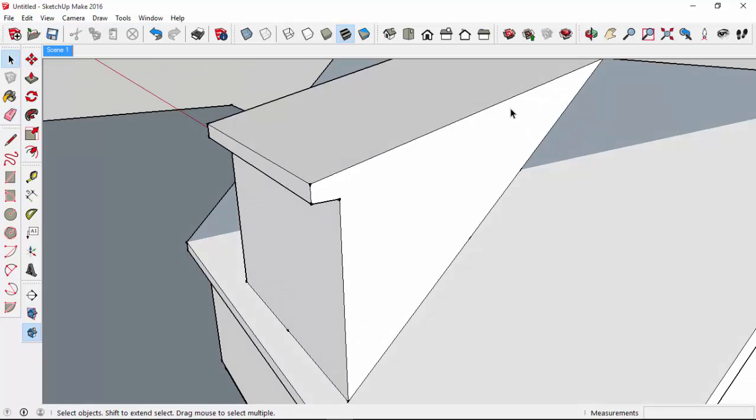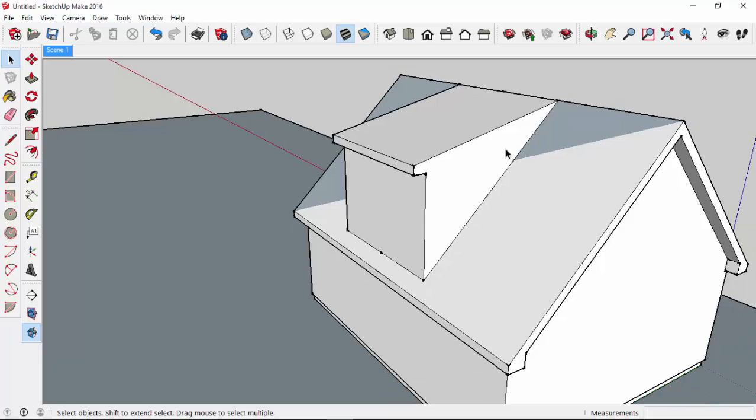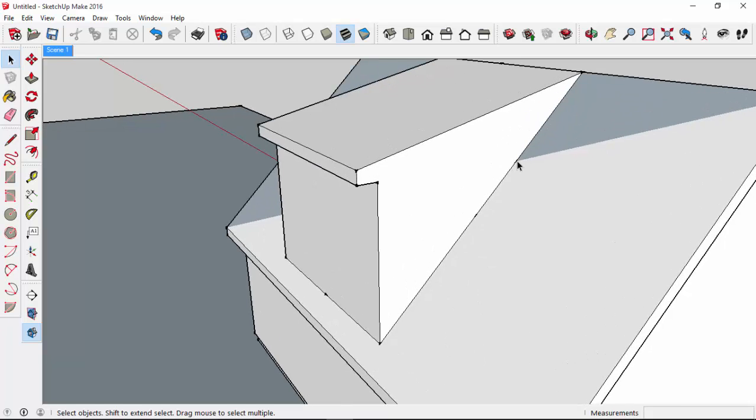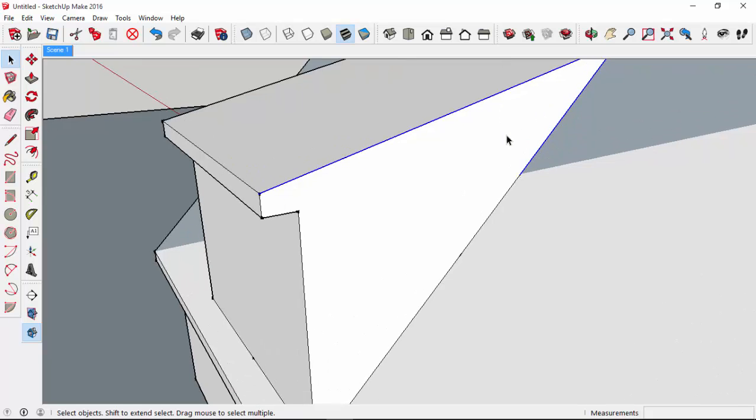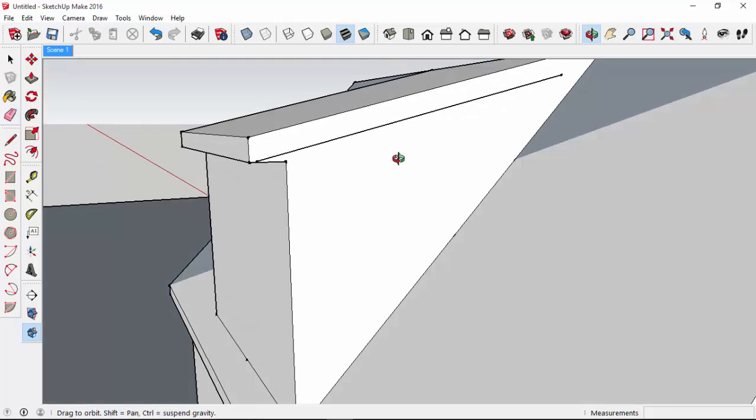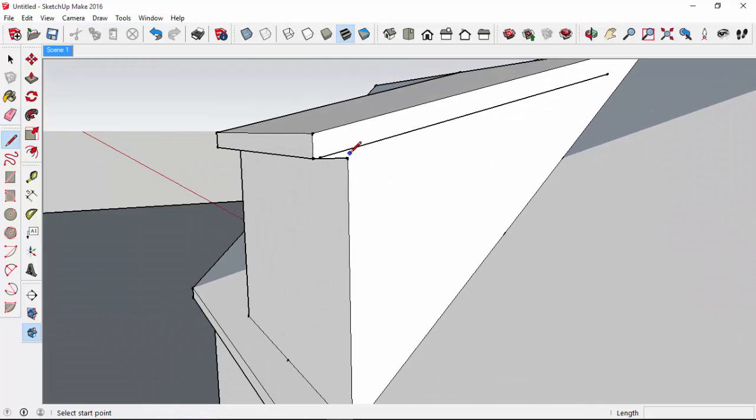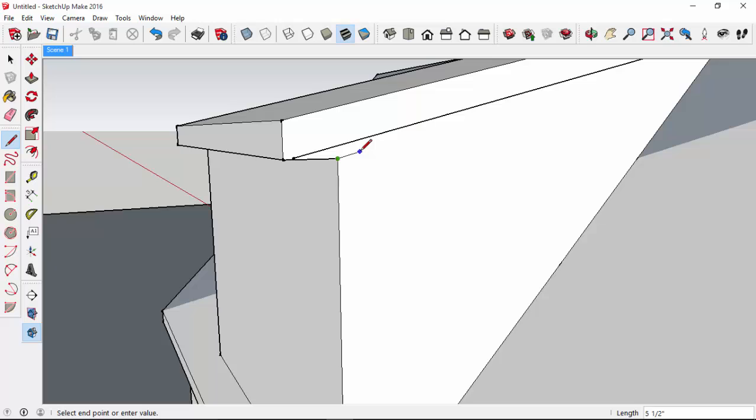And so I want to offset this down, but in SketchUp you need to have at least 2 lines selected to select for an offset of a plane. So I just select this one here just to get that. So I'll come down 8 inches, and I'm just going to erase that extra line. We'll come in here and do the 4 inches we did on the end.